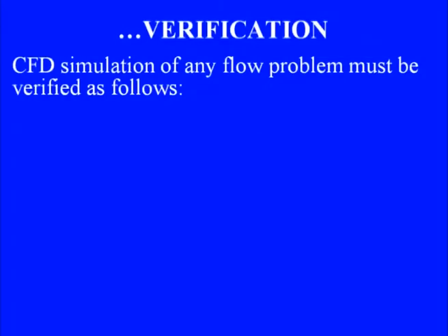So, there are two options for us. If we have an analytical solution to our problem or a simplified version, try first on that simplified version and see if our numerical simulation process matches with the analytical solution which is known to us, or then compare our solution with a high accuracy benchmark solution to complete the verification and get a quantitative bound on the accuracy of CFD results. Now, for this verification process we have to follow a few steps.